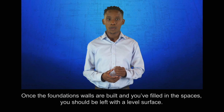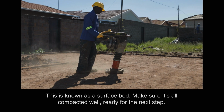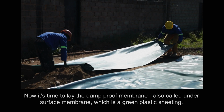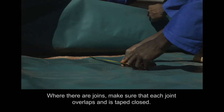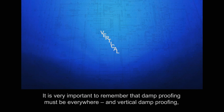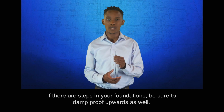Once the foundation walls are built and you filled in the spaces, you should be left with a level surface. This is known as a surface bed. Make sure it's all compacted well, ready for the next step. Now it's time to lay the damp-proof membrane, also called undersurface membrane, which is a green plastic sheeting. This needs to cover the entire surface bed from edge to edge. Where there are joins, make sure that each joint overlaps and is taped closed. It is very important to remember that damp proofing must be everywhere, and vertical damp proofing, known as damp proof course, is essential. If there are steps in your foundations, be sure to damp proof upwards as well.